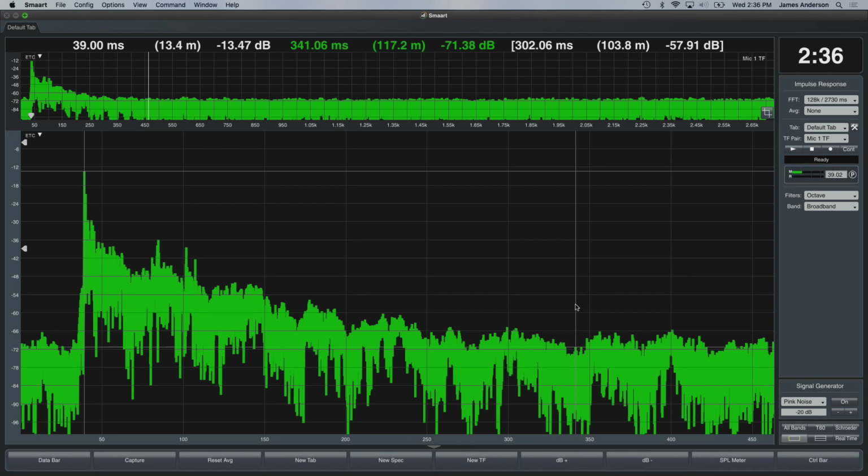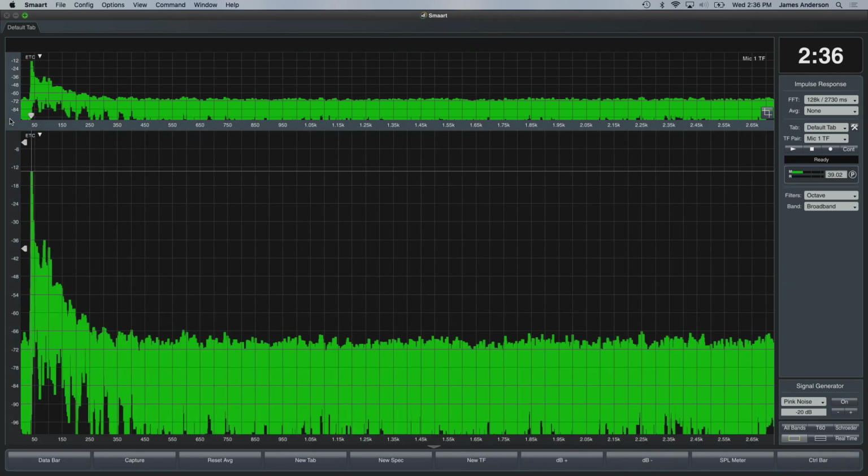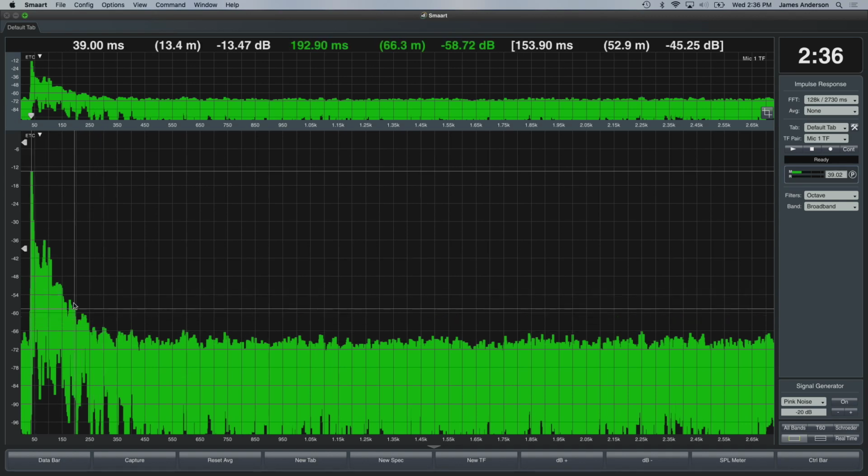So there's my broadband guy. Okay, so those four things, those will help you with this measurement. Basically, set your delay time, measure at good signal levels, good amount of averaging, and the bigger time constants, particularly if what you're trying to tell is reverberant and reflected energy from noise floor. Just using the bigger time constants is going to help.